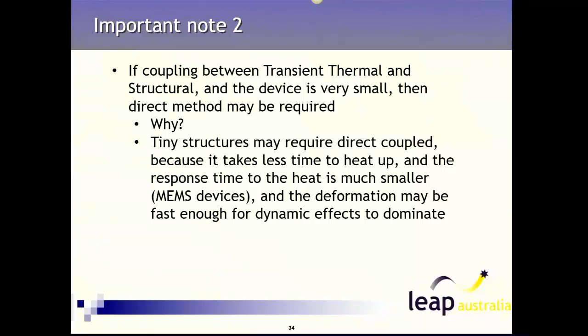Okay, so this is just reiterating with direct coupled. It's usually only tiny structures, and I'm talking tiny, fractions of a millimetre. So unless you're doing MEMS type devices or micro machines, you generally won't need to do a fully coupled solution.